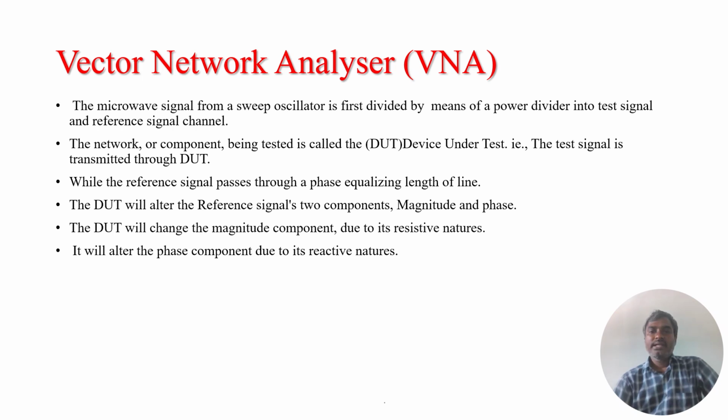The device under test will alter two important components of the signal. One is magnitude, another one is phase. The device under test will change the magnitude component due to its resistive nature. It will alter the phase component due to its reactive elements.